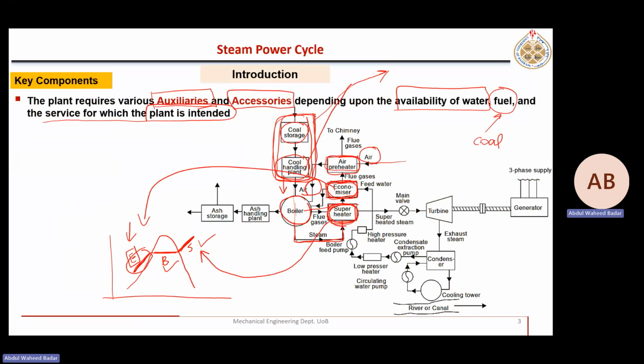So this schematic can be changed a bit. No, this is a different thing. I explained what this arrow is. So anyways, this was the fuel. Here is a furnace which we can add. Then from that furnace, fluid first goes to the superheater, then to the boiler, then to the economizer, and then to the air preheater. Now the temperature is lowest, but still the temperature is in hundreds, 300 or 400. It can be used to preheat this air which is entering at ambient temperature.